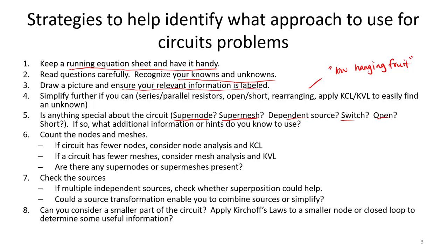Number 6 is a strategy we've mentioned in prior videos, but I think it is a very important one that is worth mentioning again. Count the nodes and meshes. And remember that node analysis and mesh analysis can both work, but sometimes one is easier than the other. If a circuit has fewer nodes, you should consider using node analysis to solve that question. You might be able to solve your entire problem with just one equation, instead of having to write several mesh equations.